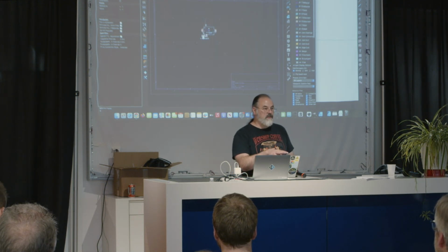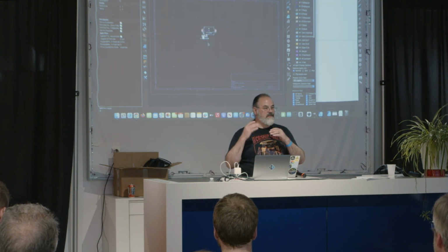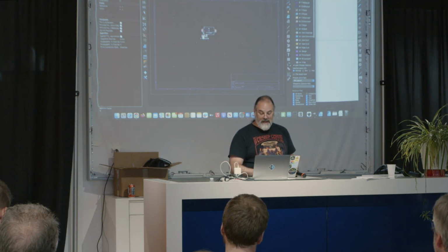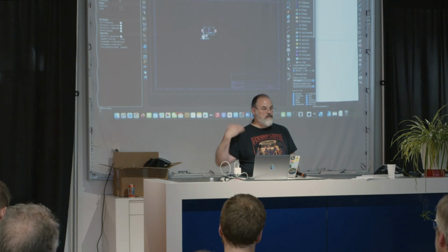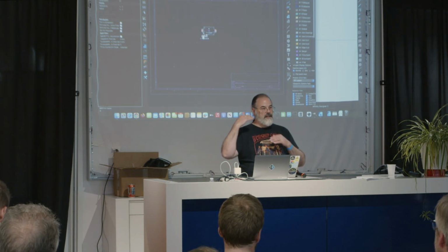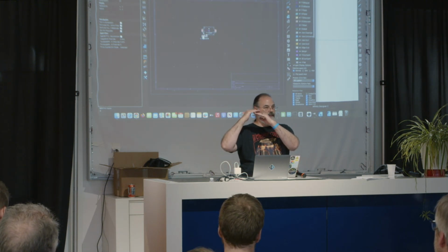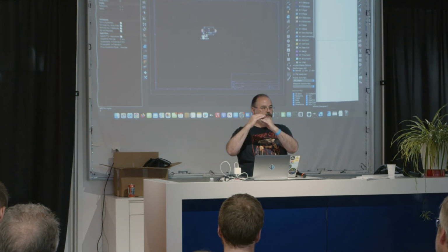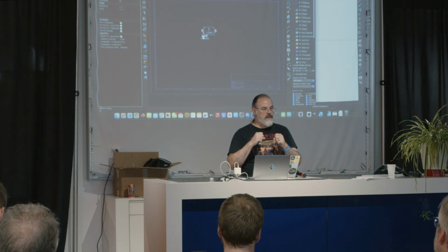I had mentioned the gingerbread tool earlier. What I have done, with Jason's help, is create a simple SVG vector art in Affinity Designer, and then exported that as an SVG, and it basically has a layer for each kind of KiCad layer. So I've got a copper layer, a mask layer where I want to pull away the solder mask, a silk screen layer, stuff like that.